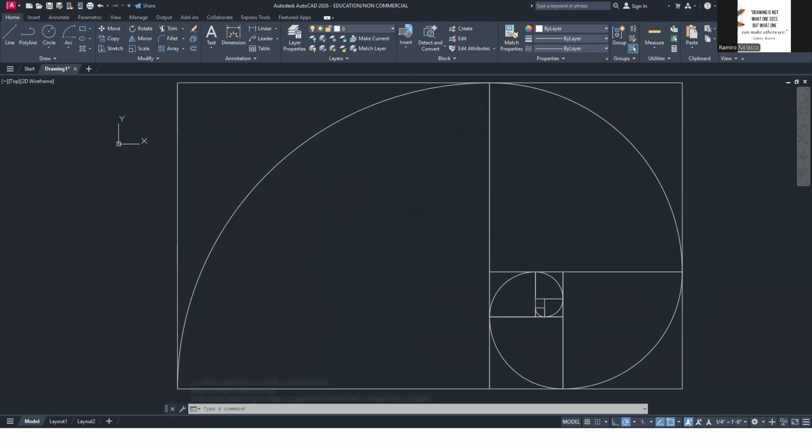Okay, so that's a nice practice activity building arcs. To communicate with AutoCAD, you issue the arc command. What is it asking for? It's asking for the start. Your arc goes counterclockwise, so you need to start from the endpoint going counterclockwise. But the next item it's asking for is the second point of the arc. We do not know the second point.